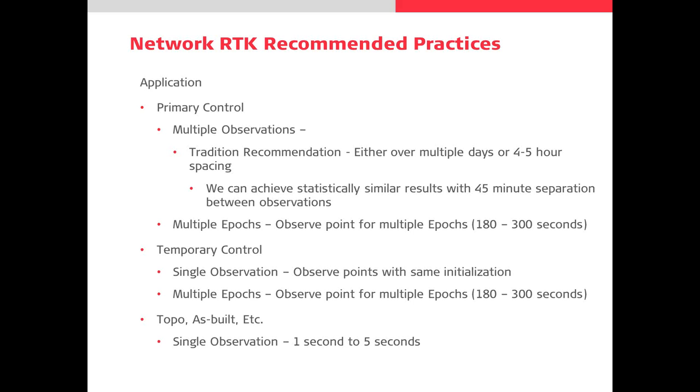So whereas we used to go out in the morning, take a shot on a point, come back in the afternoon, take another shot, and average the two to mitigate the difference in the constellations, now I can come back within 45 minutes and get statistically similar results.